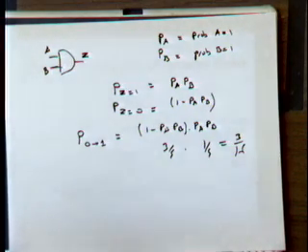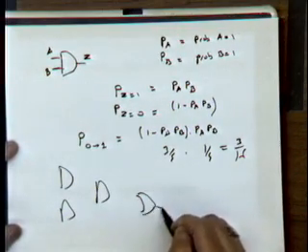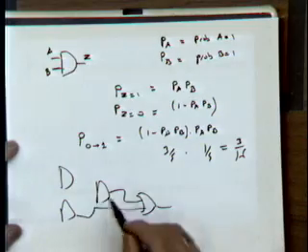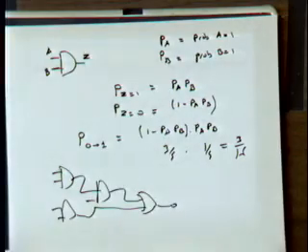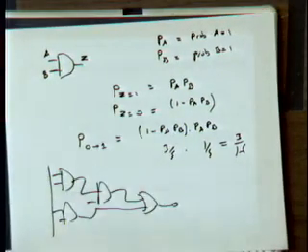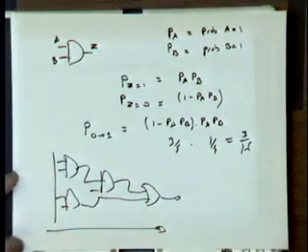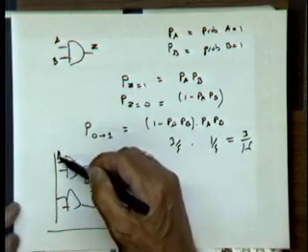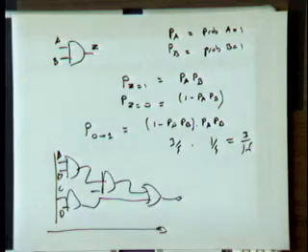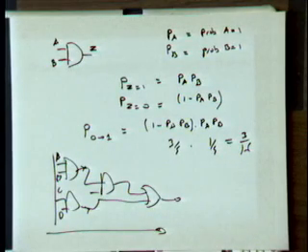So I can generalize that. Suppose now I have a complex logic block, something that has an XOR gate, and I want to compute transition probabilities. All right, suppose I have this logic function. What could I do? If I know the probabilities at the inputs, I can just move from the inputs to the output and start computing the probabilities. I know here, for instance, A, B, C, D, their probabilities. That's the input, the signals that I have. Based on this, I can compute the probabilities of having a 1 or a 0 at the output here.